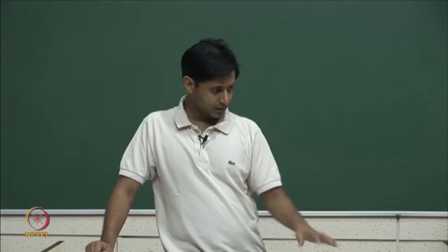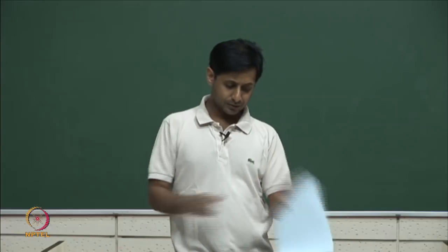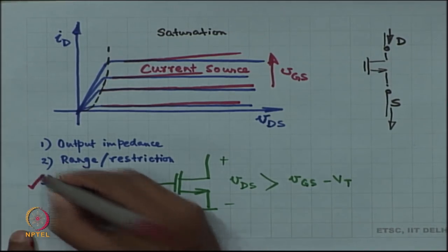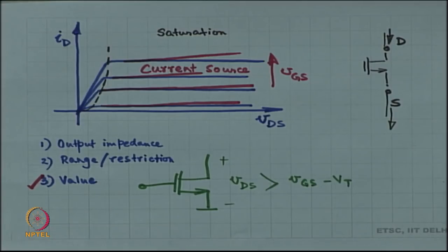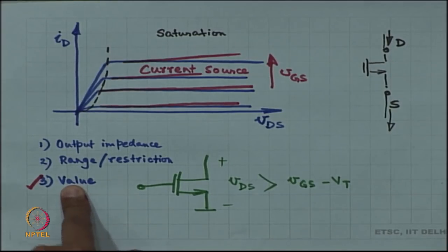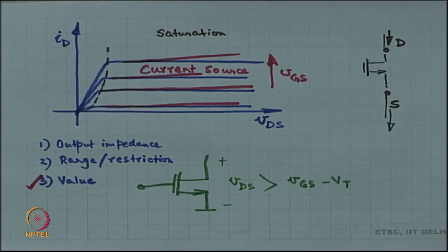Great. So, next what we are going to do is, so we have kind of solved this problem, right. In what sense? In the sense that if you give me a reference current, I can produce another current of equal value or a value proportional to the reference current.